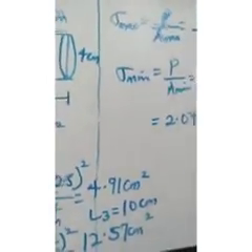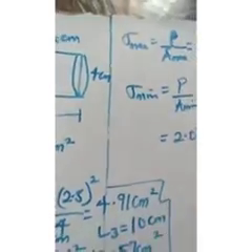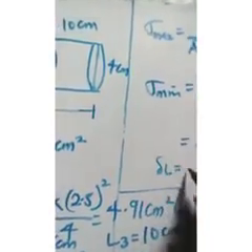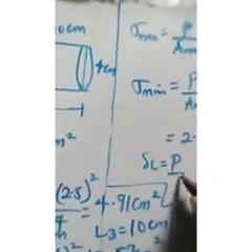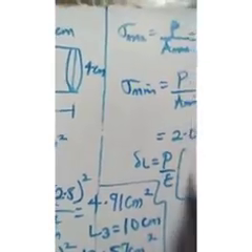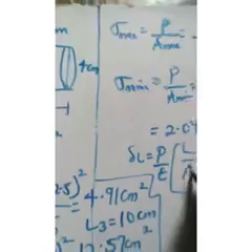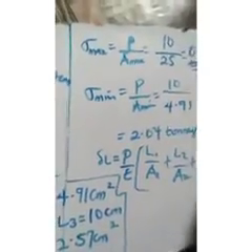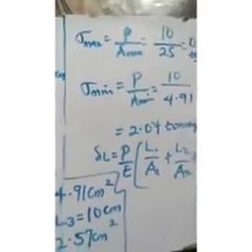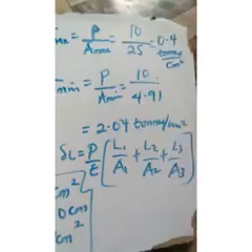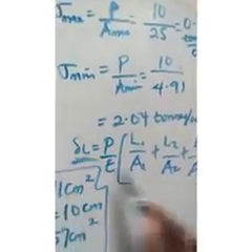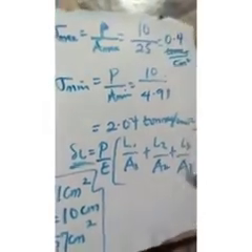Okay, now if you are to find the total elongation of the question, remember from the formula that the change in L is equal to your what? P over E into bracket L1 over A1 plus L2 over A2 plus L3 over A3. So that is to find the total elongation. You already proved the formula before, so you just plug the parameters inside.